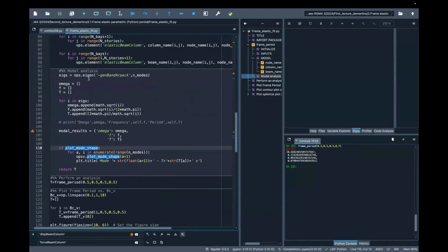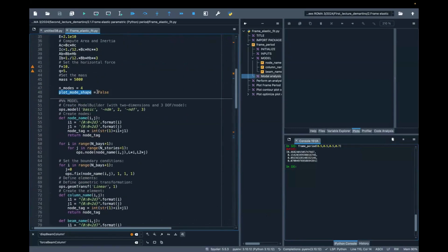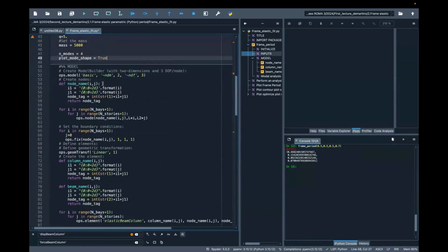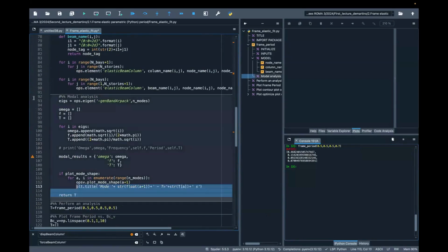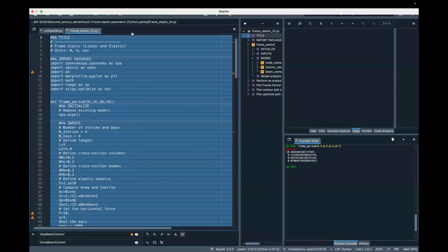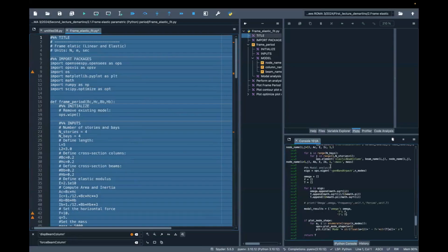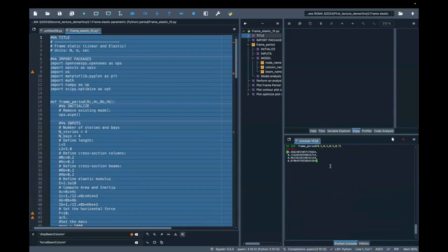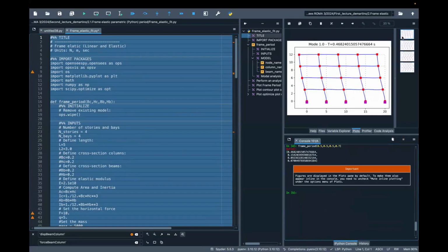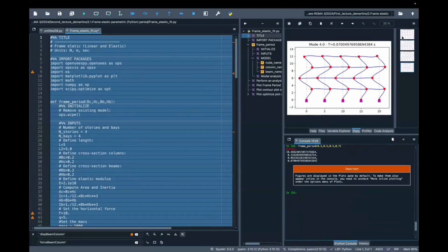Plot mode shape, right? Where is this plot mode shape? Here, so it's false, if we put true, right? And I am redefining this function, okay? Let's only show you, very easy. Tac. I'm recalling this. Additionally, I'm obtaining the typical modes of a structure like this, okay?